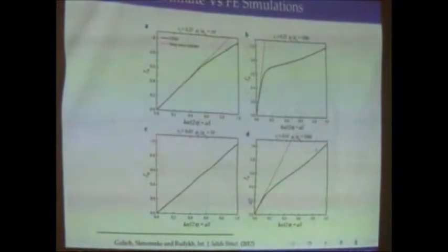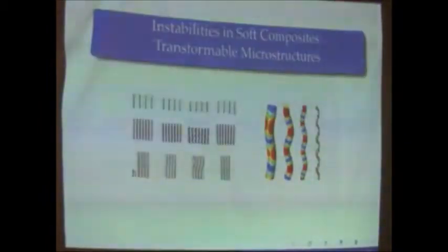And indeed, you expect that the long wave estimate will work very nicely here, but then there is very pronounced dispersion. Again, it depends on the amount of fibers that you put in and the contribution of the fibers in terms of stiffness. So with this I end the part on elastic waves and I go to instabilities.